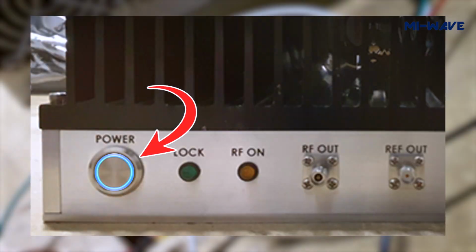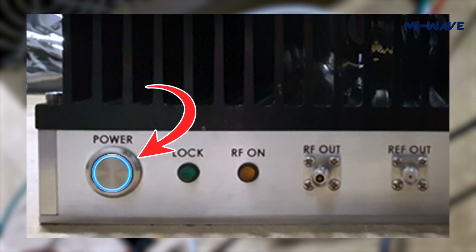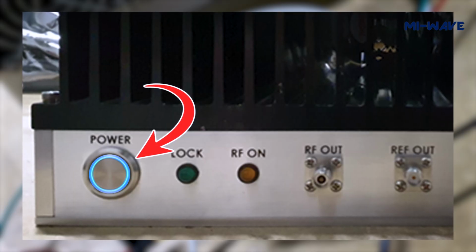Please refer to the synthesizer datasheet for exact current requirement. If current requirement is 2 amps, then the power supply must have a minimum current capability of 2 amps. Once all connections are verified, turn on the 15 volts power supply. Then press the power button on the synthesizer to turn on the unit.